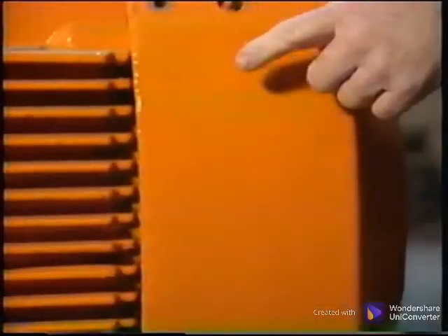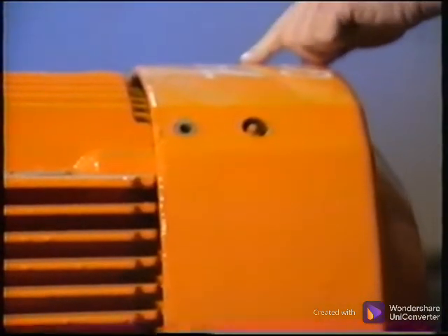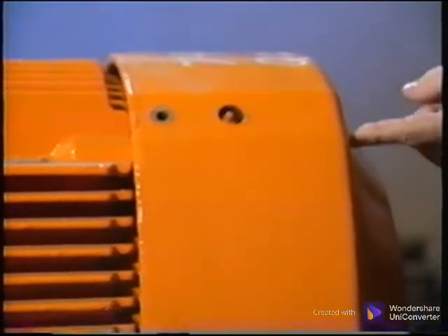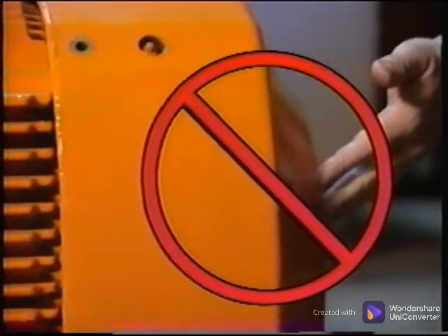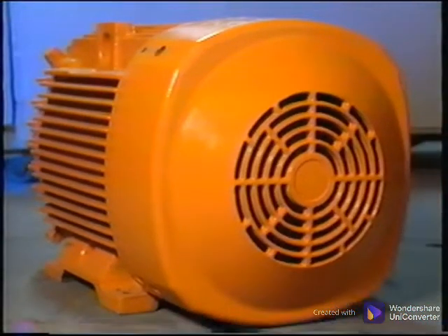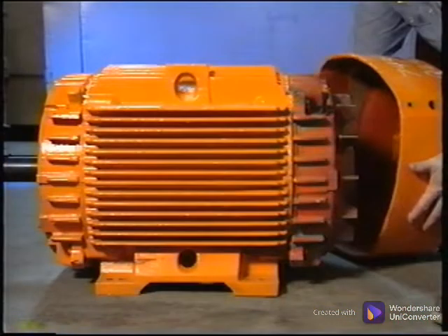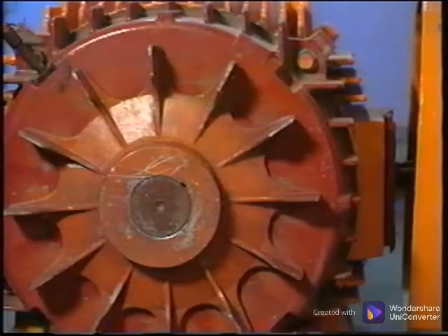The outboard end of this motor poses a special problem. The only smooth area is on this fan cover. Using its surface for mounting does not give an accurate picture of the motor vibration, but simply the energy of the cover, which may be transmitting only a very small portion of the actual machine vibration through it. With the cover removed, we can get a better idea of what we are trying to achieve.